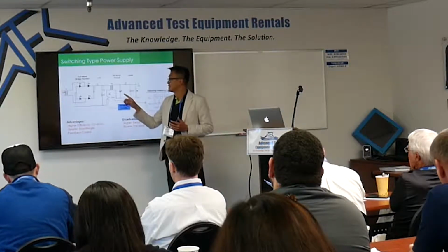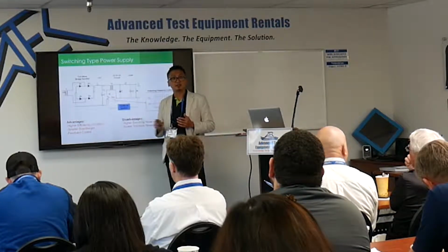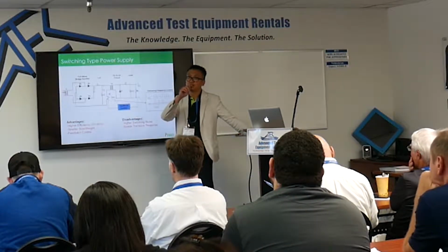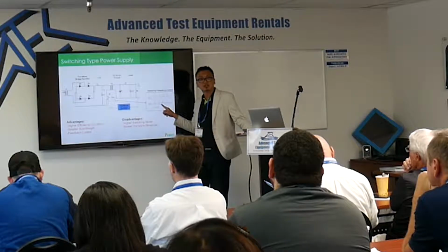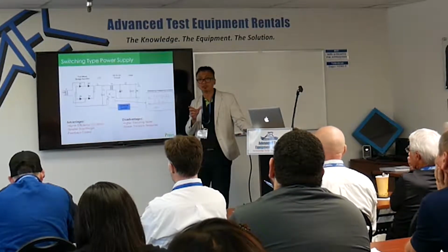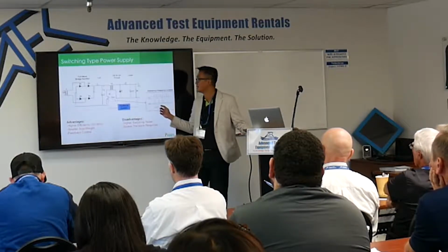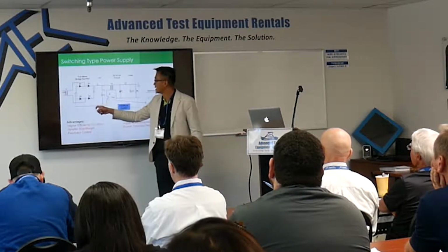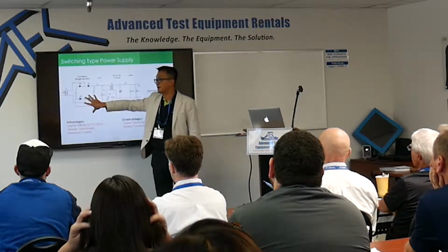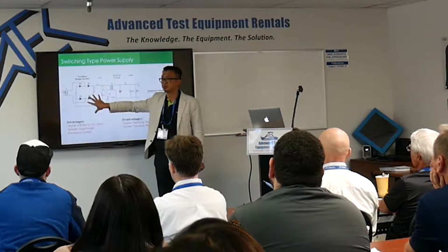So in that way, you can use what we call PWM technology. We can control a pulse to determine what voltage we want to have, and what frequency we want to have. So here we call it an inverter module, and here we call it a rectifier module.